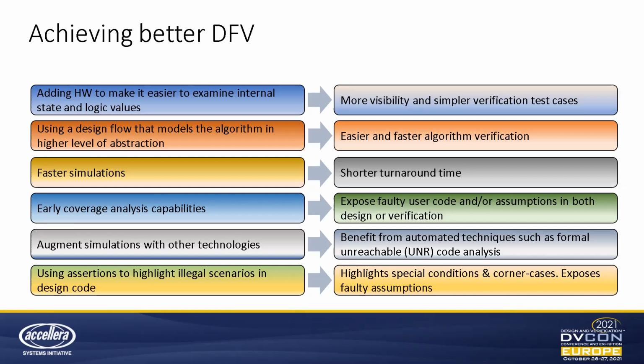Verification will be much easier by just doing a loop on the CPU or the master interface that loops on all the base addresses and reads this ID register to check that the correct module was instantiated, connected at the correct port of the bus, and is of the correct version as well. So you simply add a little bit more hardware, and you gain much more ease of verification by doing that.